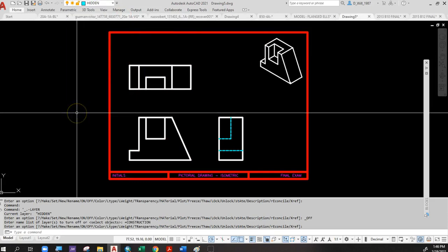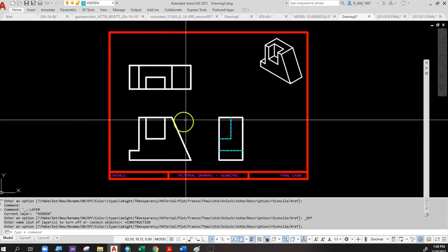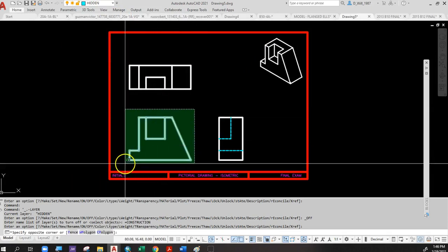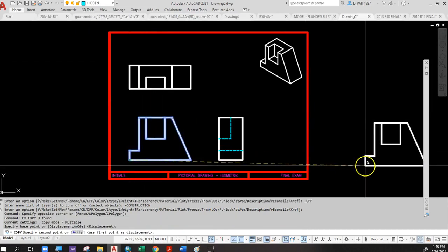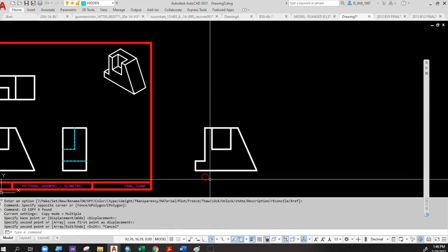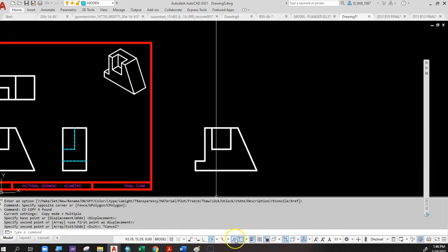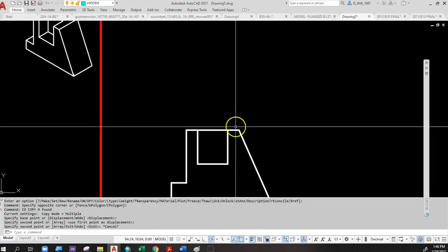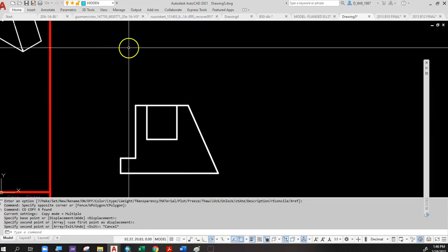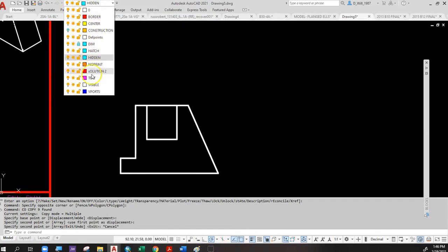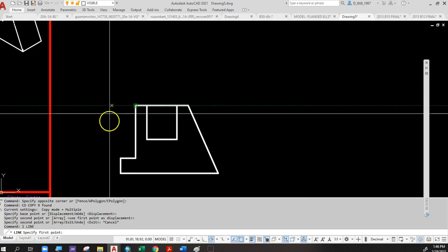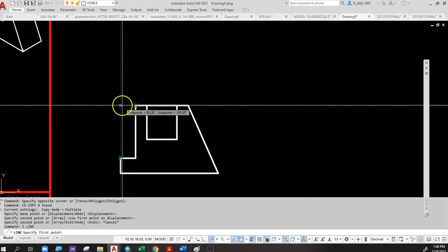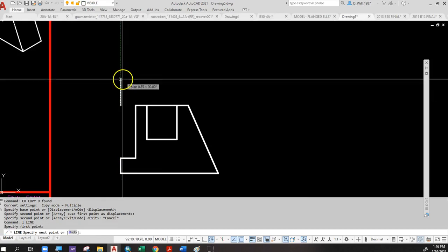Now, not everyone uses construction lines to do drawings like this. And honestly, you don't have to. Not really. You could use another tool on the Object Snap toolbar, and it's called Object Snap Tracking. So if you've never laid your eyes on this, you're going to like this, I think. Okay, I'm going to go to the visible layer. I'm going to go over to this corner, and I'm going to come up, right? And I tracked my point, and I'm going to go up 1.5 inches.